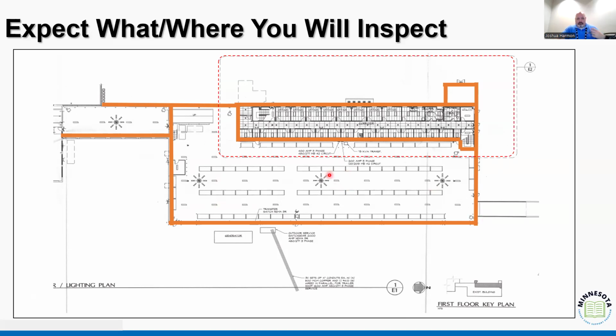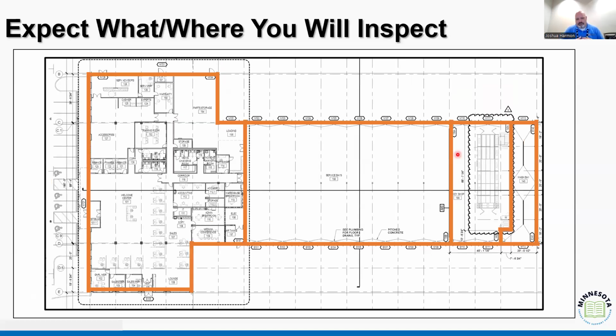We were expecting big fans to provide ventilation and one gas-fired heater to keep it semi-heated because it was a warehouse. And then you throw in 60 offices. Well, guess what? Now we have to either condition and control the entire space or isolate and separate those offices, right? And again, we're not talking a simplified system. We're talking craziness when you start to do those kinds of things, which is why we need to have as much information in the process.